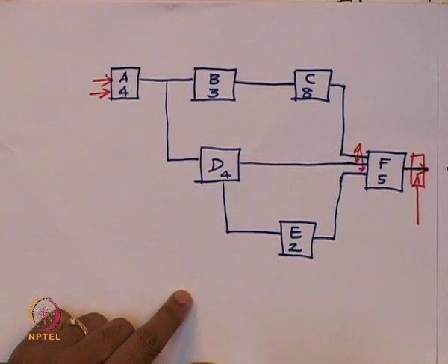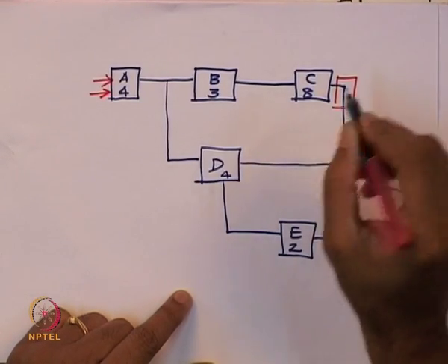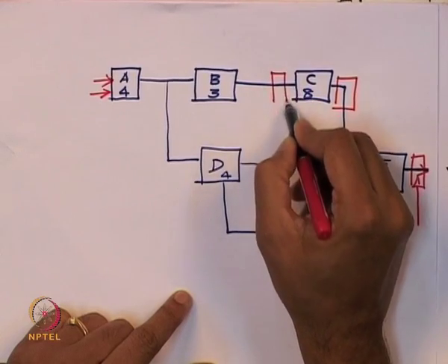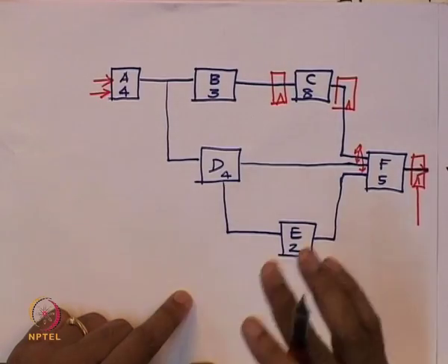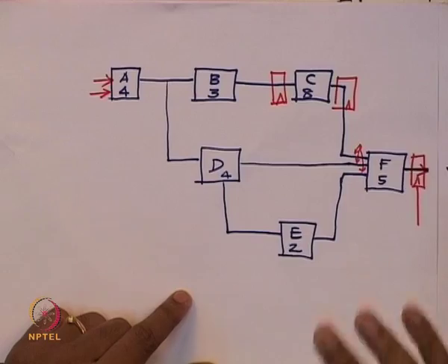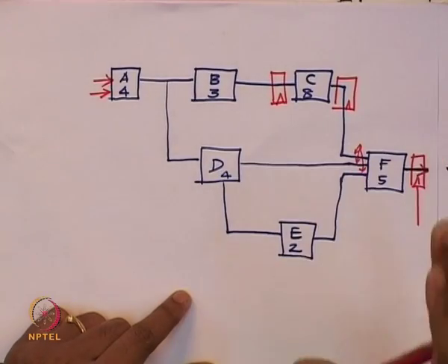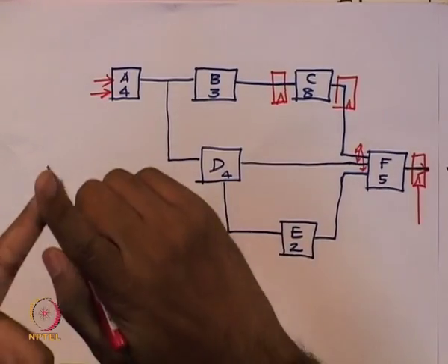So what I am going to do is put a flip flop at both the inputs and output of C. So I am talking about a methodology, which I will summarize later. Let us take this specific example and see how to pipeline this circuit in a correct manner. There are 2 goals to the pipeline.